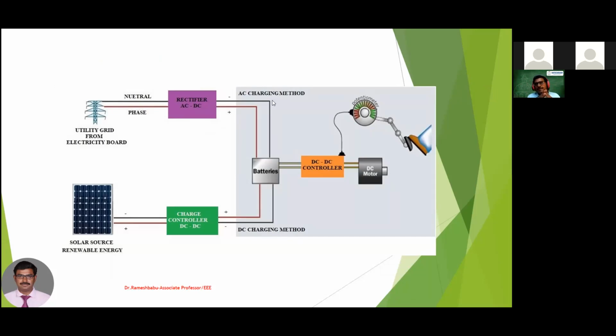Okay, so you can see, I'm going to use a DC motor as a traction motor. In the figure here you can see it is a DC motor. If it is a DC motor, I need a DC supply as input. There are two types of electrical supply, AC and DC. In our homes, all the appliances use AC supply. If we use a DC motor as a traction motor, you need to have variable DC as an input for the DC motor. To get variable DC, we need a DC to DC converter.